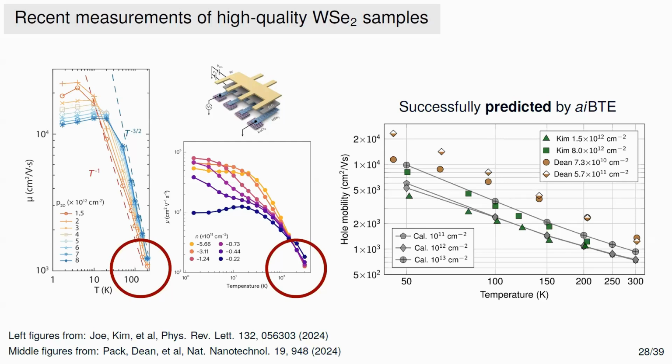One could also ask why these other data are a little bit above what you see. Actually, we don't have a full explanation yet, but we believe this is happening because in this other setup by the Columbia group, they also have a graphene layer below the dielectric, and this graphene layer is screening the impurity scattering in their samples a little bit. That should bring the mobility up a little bit. So that's something we're currently exploring, to see whether one can even boost the mobility of the single material by adding some kind of semi-metallic layer like graphene to help.